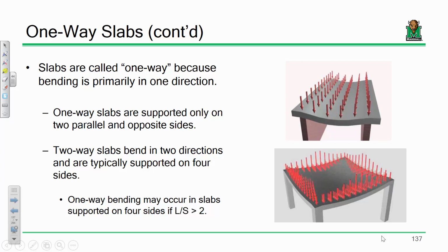So imagine if I could take my floor system and I could go from this with a one-way slab to this with a two-way slab. That doesn't seem like a lot, but imagine I have a height limit in Washington, D.C., and so I only have so many stories. Well, maybe this to this doesn't mean much, but maybe after 30 stories, I save so much height I can put another story in the building. Another story in the building is a whole other few hundred square feet I can rent out and make some money. So that's a very real application.